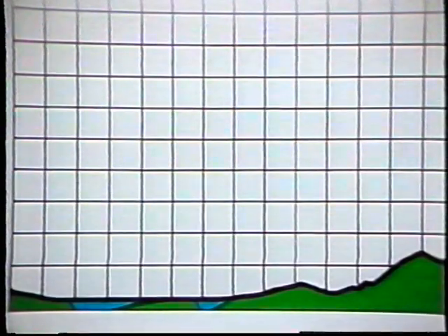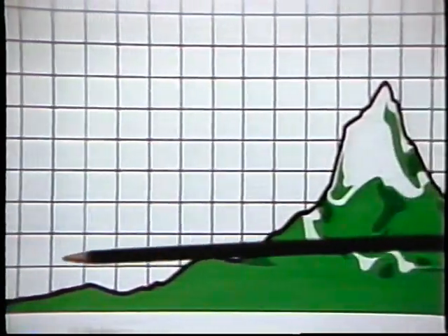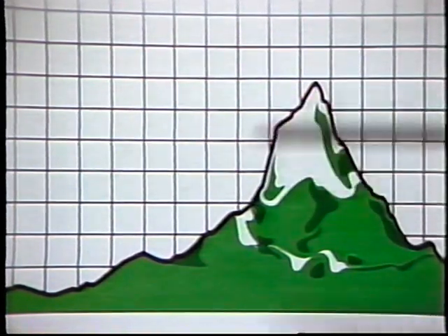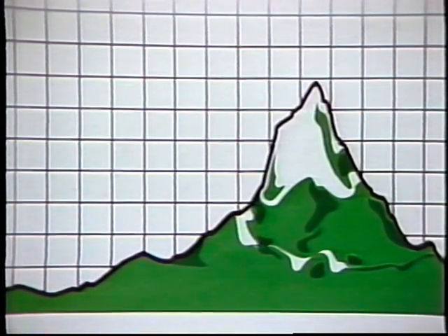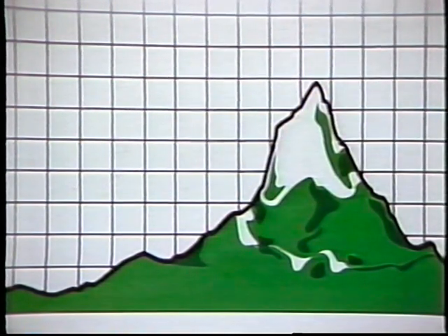That means you'd want to select a compressor with a capacity larger than if the same system were going to operate at sea level. The main point to remember is that as altitude increases, the output capacity of an air compressor decreases. It is more critical with single-stage compressors, but is also a factor with multi-stage units.